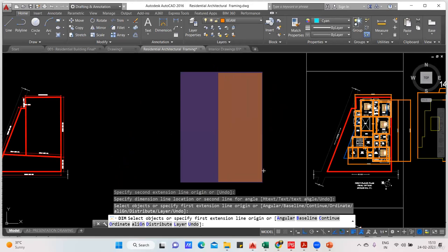This complete length I utilized. Then what shall I do? Because from here I don't have any space, as my plot boundary itself is this one, and I did my construction on the outer side. So this side I cannot take 1 meter, sir. This side also I cannot take 1 meter. Then no problem. You will have certain space in this area, right? You utilize this space and do the calculation. But remember one thing, the client is going to pay you only for 1 meter extra. You cannot say I have done extra cleaning here. No, the client is not going to pay you. The client says that I will give you 1 meter from this side, 1 meter, 1 meter and 1 meter. Within this, you have to store your material.